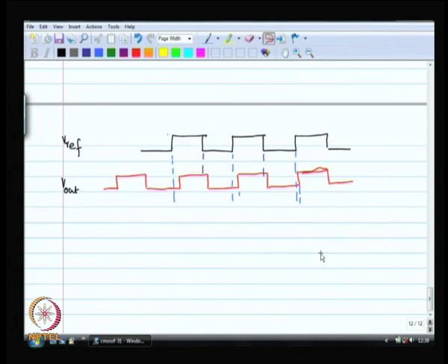First of all, I should not be caring about both edges. I mean, the duty cycle of my 2 clocks could be different. So, it is unreasonable to compare both rising and falling edges, right. So, that is also something that you have to keep in mind, that you do not necessarily want to compare both rising as well as the falling edge. So, this is what I want.